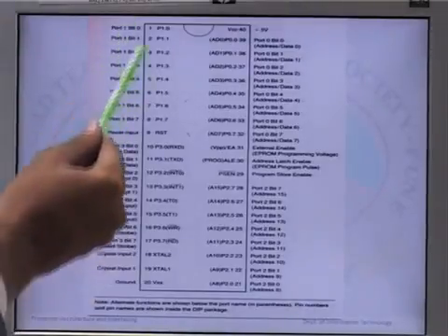Pins 1 to 8, as shown here, are nothing but the port 1 pins. Port 1, each of these pins can be configured as an input or an output. Pin number 9 is RST. RST stands for reset. Logic 1 on this pin disables the microcontroller and clears the contents of most registers. In other words, the positive voltage on this pin resets the microcontroller. By applying logic 0 to this pin, the program starts execution from the beginning.